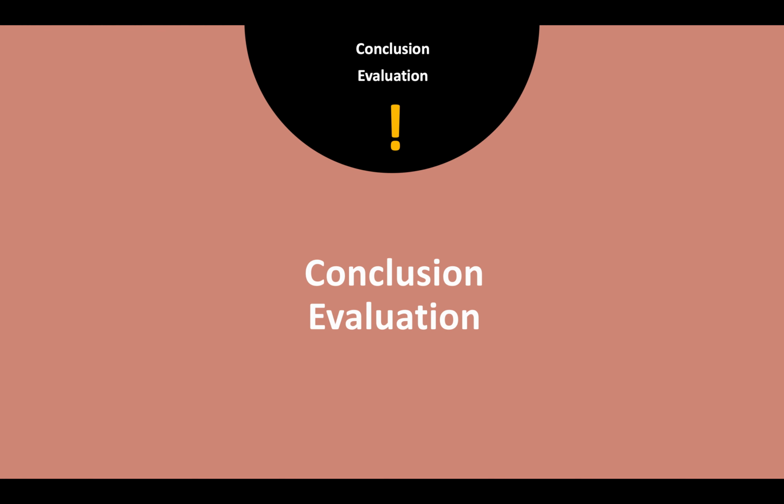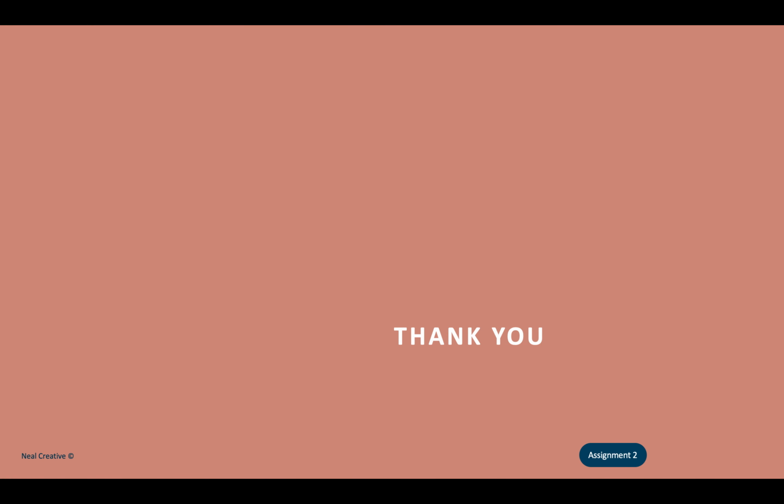So, in the assignment, I have shown how to use Prosper and calculate the IPR and the VLP curve with different pressure and skin factor. As can be seen from the previous slide, when the skin factor increases, the flow rate decreases slightly. Furthermore, I have already designed a simple well by using the gas lift method. It also shows that the pressure will increase and the temperature also goes up when the depth gets higher. All in all, Prosper is useful software for engineers to solve some problems in this field to support the engineer well. So thank you for listening.